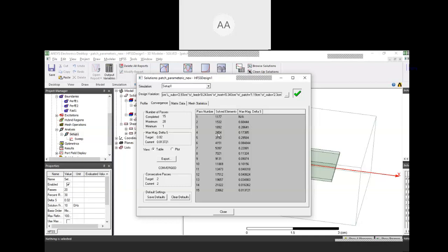So it keeps on increasing the number of elements and does the iteration again. What you can see out here is one thing, at 2454 elements, the value between the previous and the new elements has come down to 0.17385. To give a clearer picture, you can assume, let's say, a Gauss-Seidel method is running, or Gauss-Jordan, or even the bisection method. In all these three cases, we compare the results of the new case with the previous case. These are computational techniques. In the Gauss technique, we plug in the values x, y, z as 0, 0, 0, find the value of z, then find the value of y, then find the value of x.